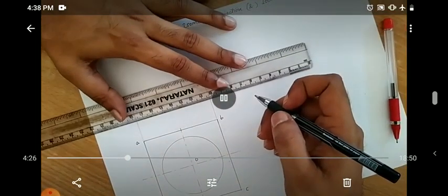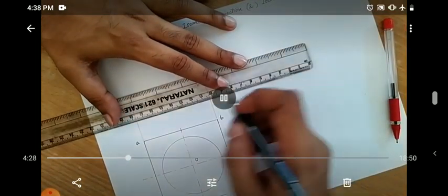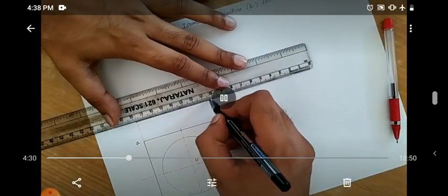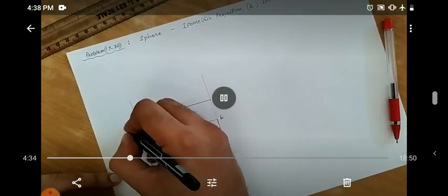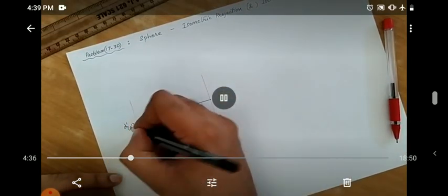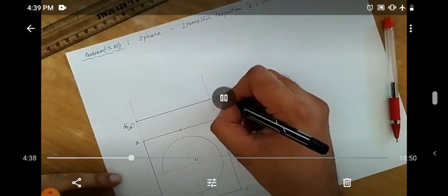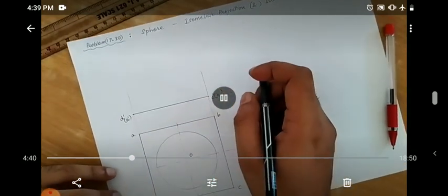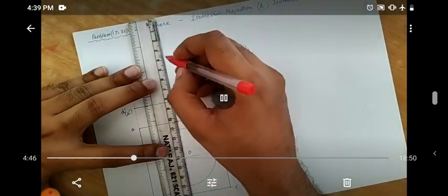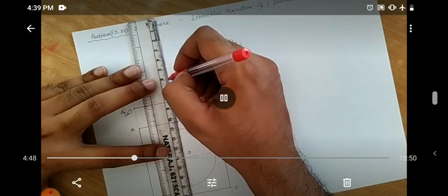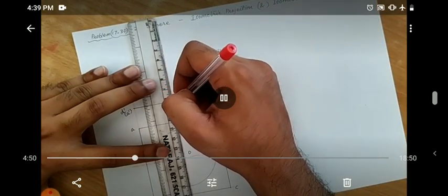Now when we draw the front view, the square lamina, square area will be viewed as a single line because that is an area without any thickness. And from that center point, the namings are given accordingly now, and from that center point you have to take the height up to the center of the sphere. The height up to the center of the sphere will be exactly same as the radius of the sphere.